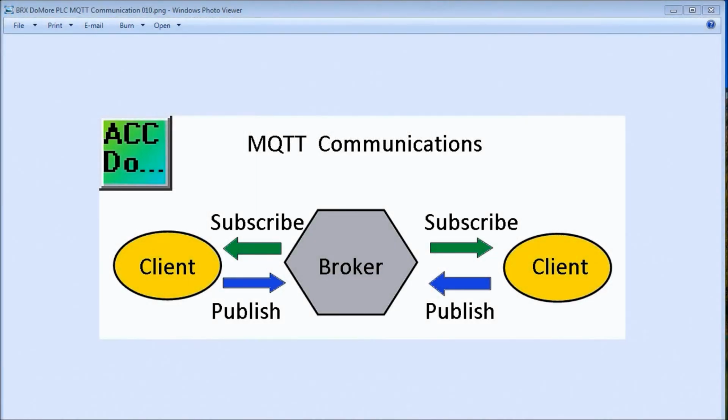Hi everyone, today we are going to be looking at the BRX Do More PLC MQTT communications. MQTT stands for Message Queuing Telemetry Transport. This simple publish and subscribe communication protocol does not take too many resources. Constrained devices with low bandwidth are ideal for MQTT.